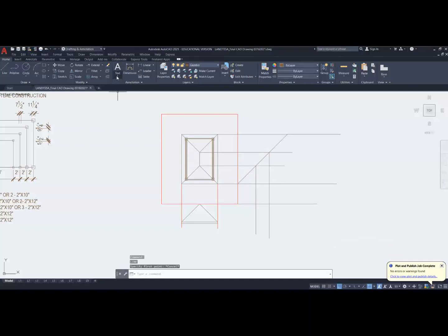I can also take this and mirror that image. So I'm going to select mirror, and I'm going to pick the design elements, the strategic elements of that roof, and I'm going to mirror it from here to here. And you notice it's upside down, no problem. What I'm going to do is mirror the back side of it. And that will actually show up in the correct direction here. Now, because I mirrored the backside and the way this actually worked out, I'm just going to move this from here to here. So that's one way of doing it.